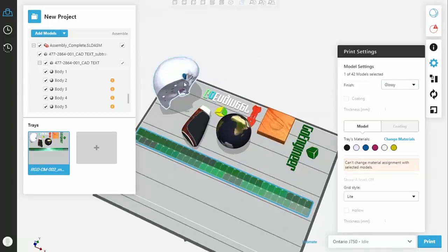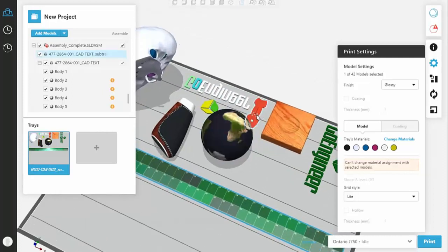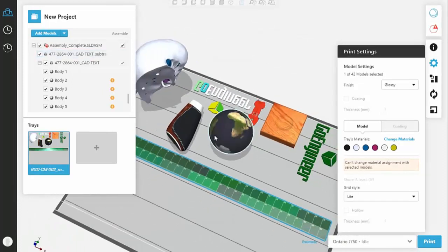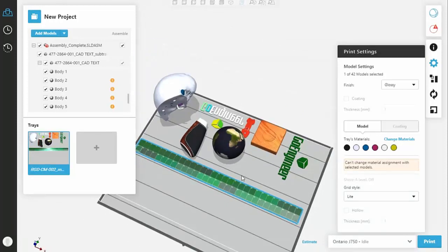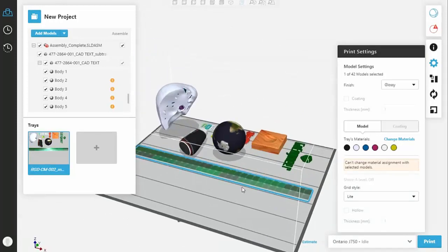Again, all the different methods: shell-based, assigning colors right in SolidWorks, creating simulated textures in SolidWorks, actually applying textures to meshes in Photoshop, bringing in complex VRML files, doing hard color proofing using the swatch generator tool. There we see the single tray showing everything that we've just highlighted. What I like about this is because we're printing in a full color configuration, cyan, magenta, yellow, black, white, clear, literally all of these projects can be done at the same time as a part of the same build.